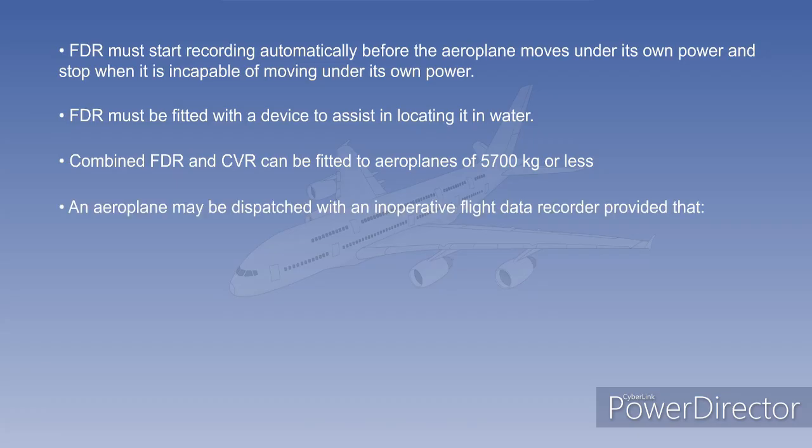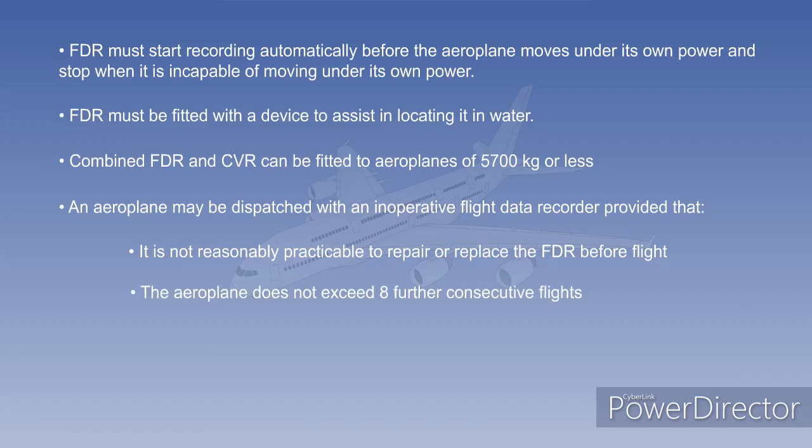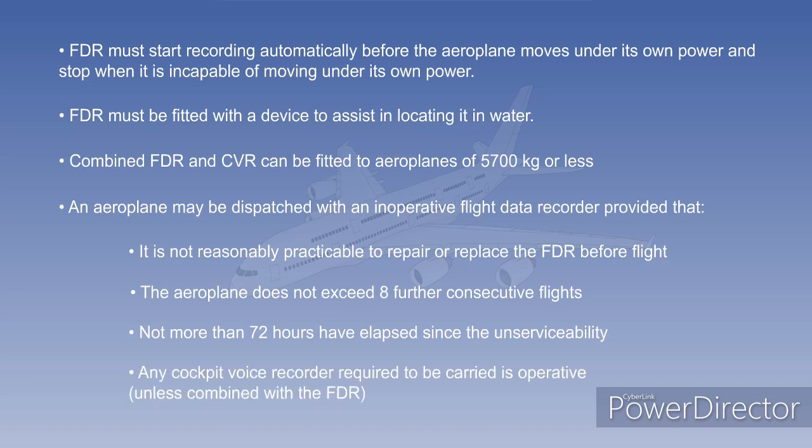An aeroplane may be dispatched with an inoperative flight data recorder, provided that it is not reasonably practical to repair or replace it before the flight, the aeroplane does not exceed 8 further consecutive flights, not more than 72 hours have elapsed since the unserviceability, and any cockpit voice recorder required to be carried is operative unless it is a combined unit.